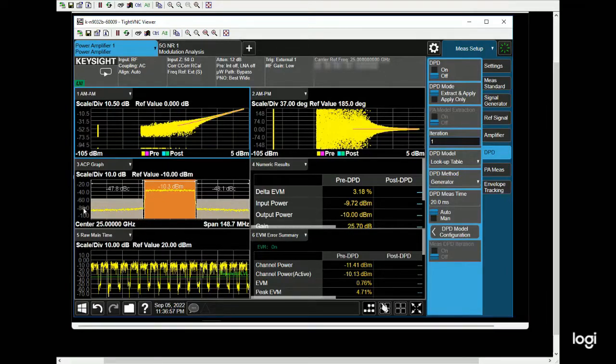Although based on this plot here, you might not have much improvements, in fact, because it's pretty much in the linear region. But if you have an amplifier in the test, you'll be able to adjust the power levels to just about to hit compression or the non-linearity region, and that would create a much more accurate DPD model.